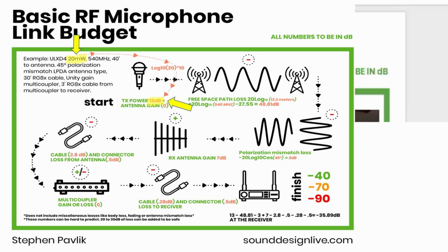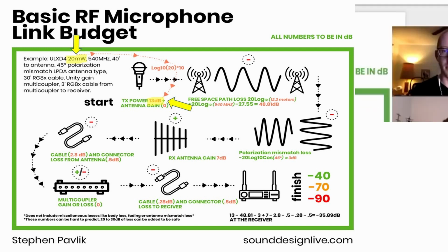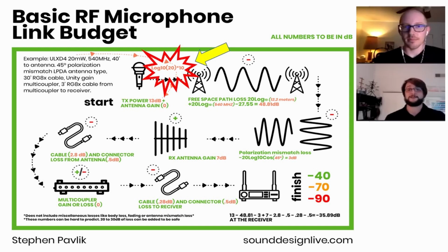Got it. Okay, great. Yeah, and that's a good one to memorize because we do most things in dB as engineers in all fields. Audio, RF, dB is our friend. Great. The rest of it I think is pretty clear. And then in the end, you just added all those numbers up and got your final number. And you said, hey, negative is good. That's up into the green number, right? Yep. And I said we're going to assume a little bit more loss from that, but we have that much power getting into that negative 40 region. That loss is going to put us still in a very good area. So anywhere around that green, and we're good.